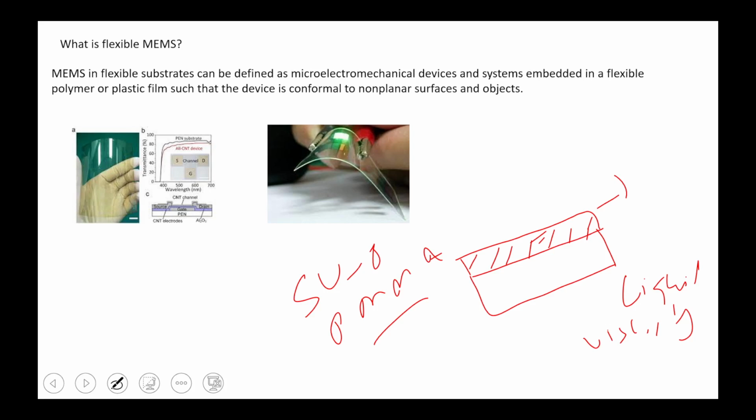Some water molecules will remain on that surface, and we cannot expose the UV light to the photoresist in liquid form. Also, for adhesiveness of the photoresist to the substrate, we require the soft baking. Sir, can't we do hard baking directly?